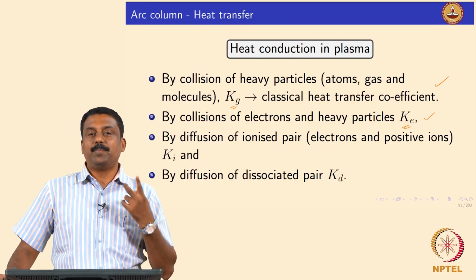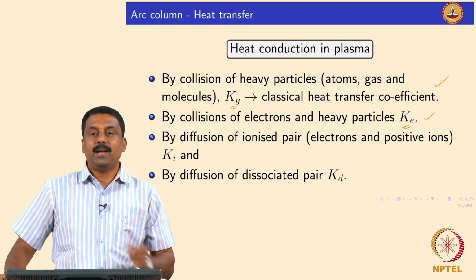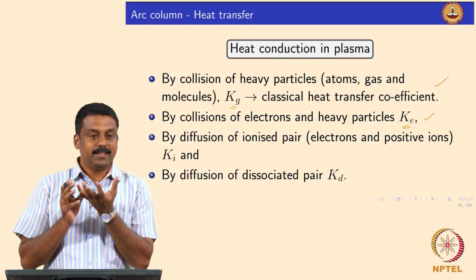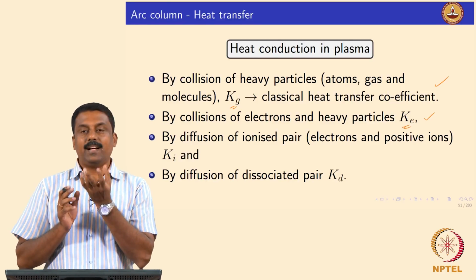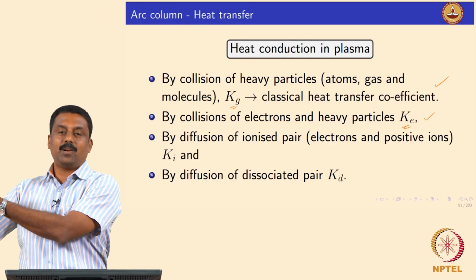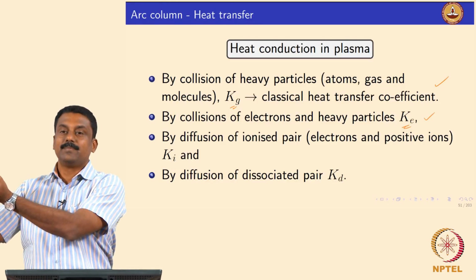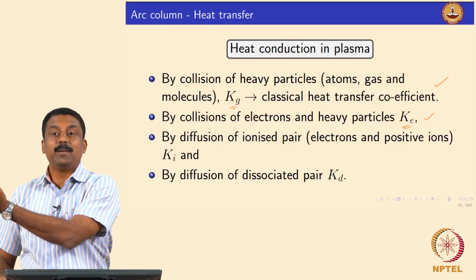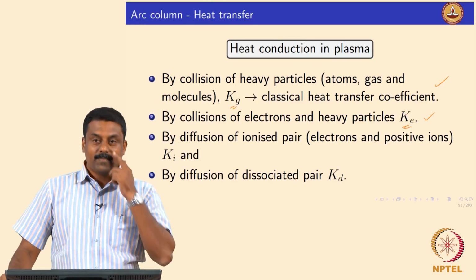And 2 other phenomena are also possible because of the ionization. Imagine there is an argon atom here inside the arc, it ionizes, okay? And the ionized argon atom, argon plus, goes over here. It is attracted by an electron, diffuses again back to this argon plus, it becomes an argon atom, and that is an exothermic process, because electron gain is an exothermic process, isn't it?